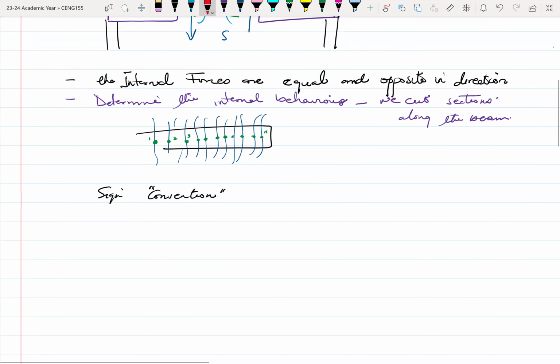So I think we said that if we have a point, let's say this point can be point 1, point 2, point 3, all the way to point 11, like what I have in this case, all right? So if you have a point and then you have your axial forces, let me use a different color, axial forces going away towards the left, on the left of the point, we call that positive.